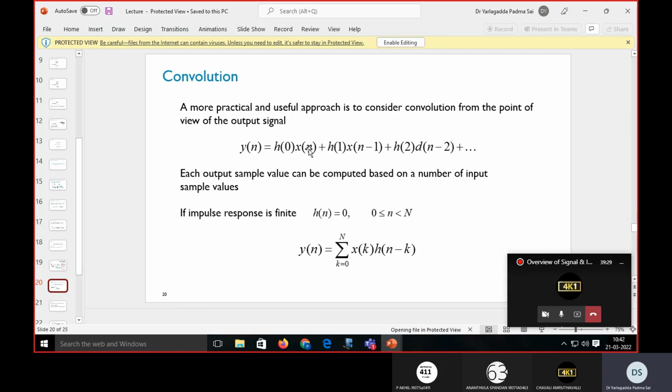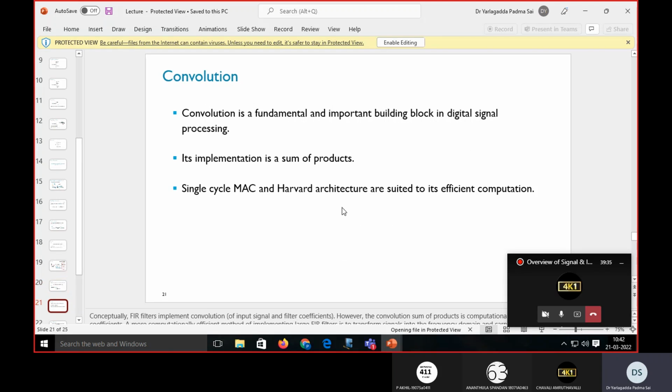So for convolution, we expand the summation and substitute different values. How do we implement this on a processor? In a microprocessor, you don't have any multiply instruction; if you want to multiply, you shift and add. In a microcontroller you have a software multiply, so the number of clock cycles is reduced a little bit. But in all DSPs you have dedicated hardware units available.